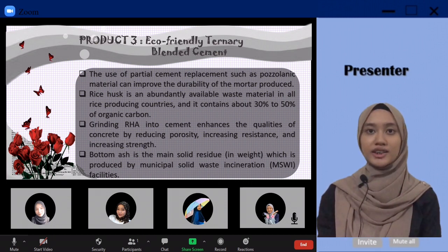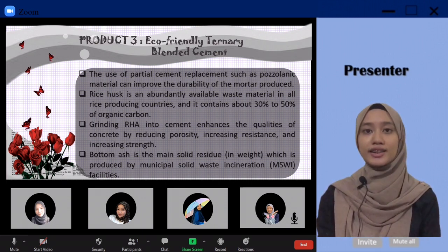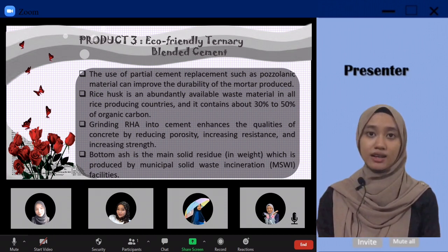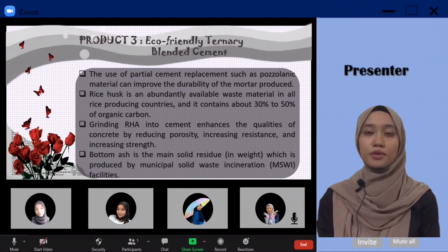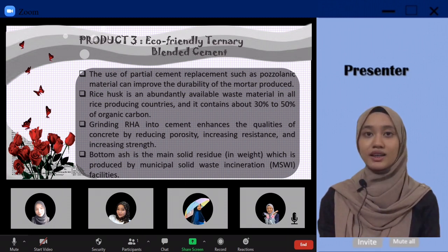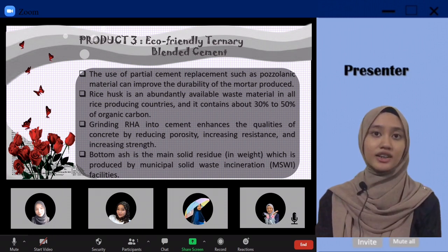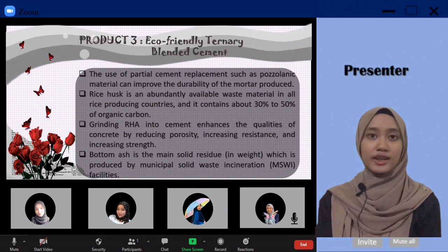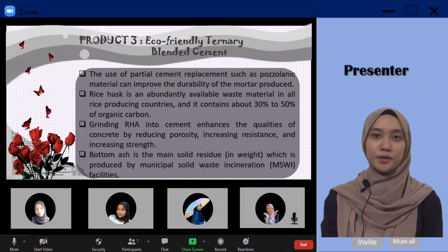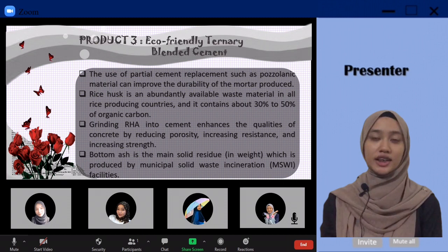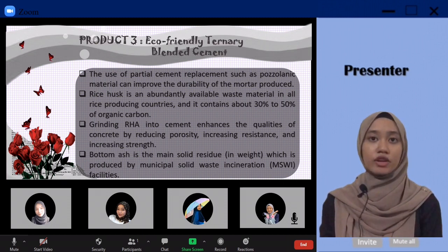The chemical reaction that occurs in Portland cement when pozzolans are added and react with water is called a pozzolanic reaction. In this reaction, silica, whose precursors lack cementing properties, converts into a calcium silicate with good cementing properties. In chemical terms, the pozzolanic reaction occurs when calcium hydroxide, also known as portlandite, reacts with silicic acid to form calcium silicate hydrate. The pozzolanic reaction is a long-term reaction that includes silicic acid, water, and CaO. This may be irreversible. A high amount of free calcium at pH 12 or above is needed to initiate the pozzolanic reaction.